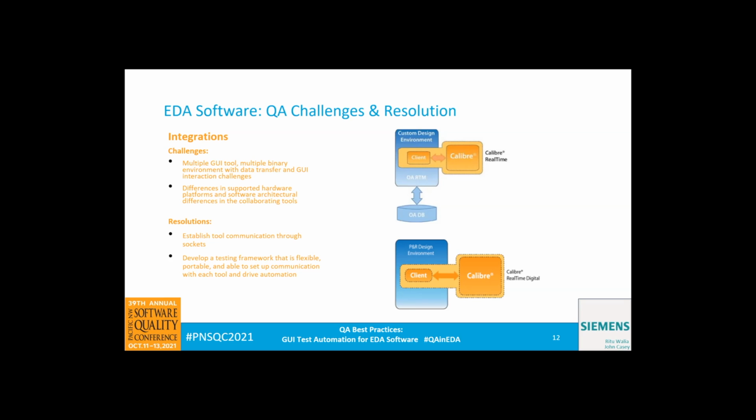There are different tools that customers use depending on whether they're designing a digital circuit or an analog circuit. If they're designing a GPU or a CPU, they'd perform the creation in a digital place and route tool. And if they were designing an analog circuit like an op-amp amplifier, then they would use a different set of tools, a custom layout tool.